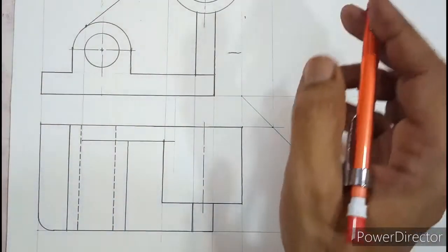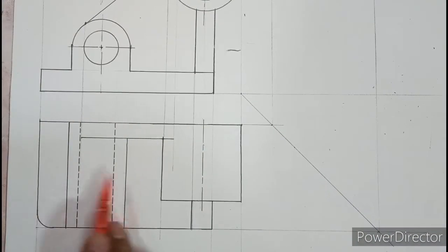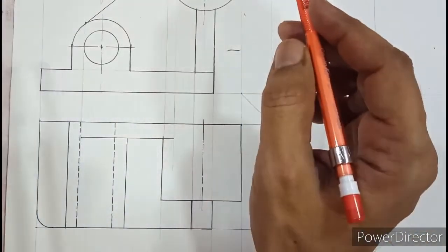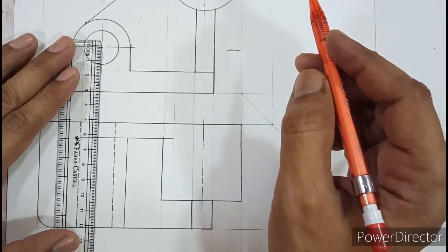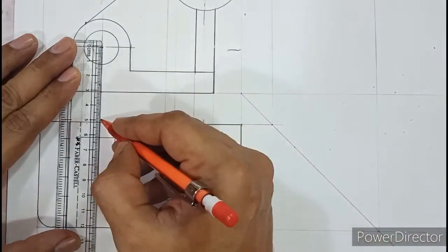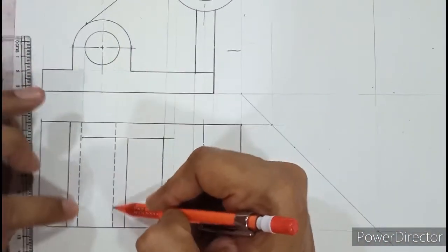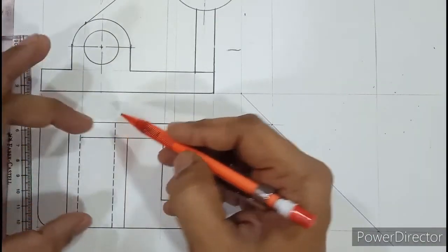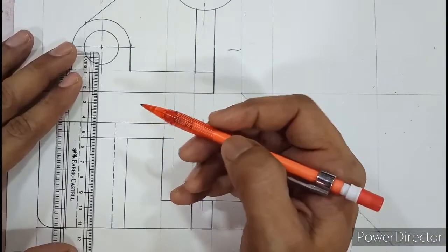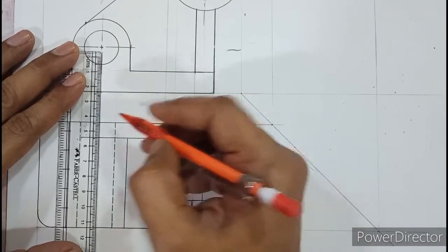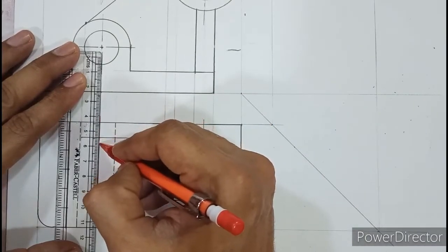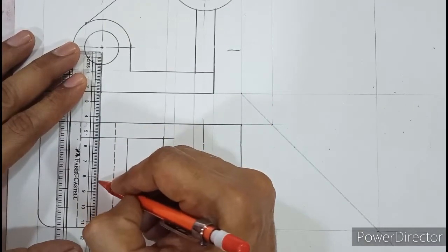That doesn't matter. Now because this is a circular surface, it has to be supported by, yes, axis line. So let me align the axis line over here. Now because the circular surface, the inner circular surface is longer, I need to extend the axis line slightly beyond that. So over here, big dash and small dash.